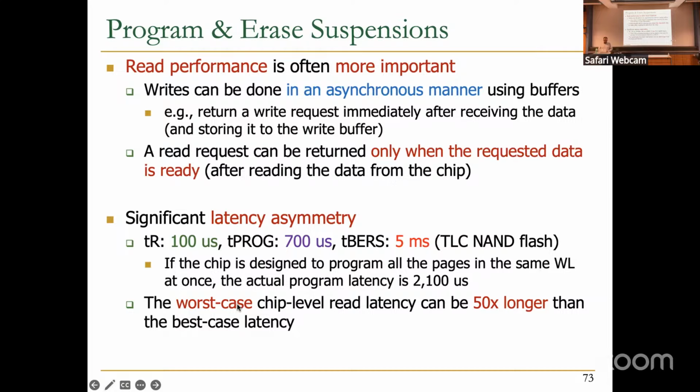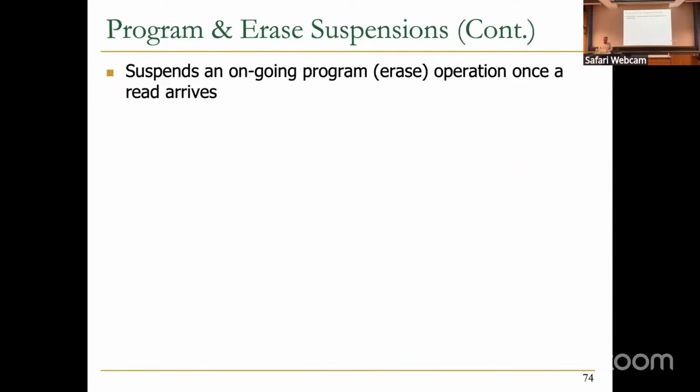So the worst case chip level read latency can be 50 times longer than the best case latency, assuming that you are very unlucky and that the read is queued after a write operation. So that's very bad. So that's why people try to suspend an ongoing program, which can also be an ongoing erase,